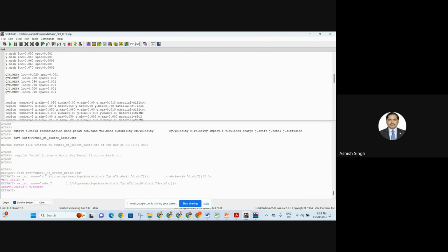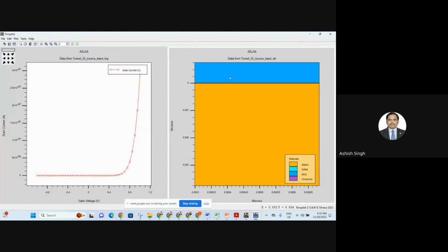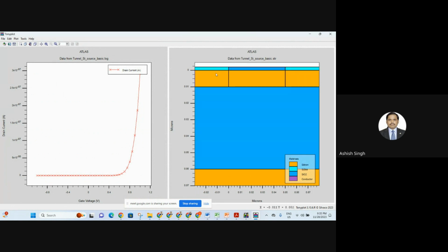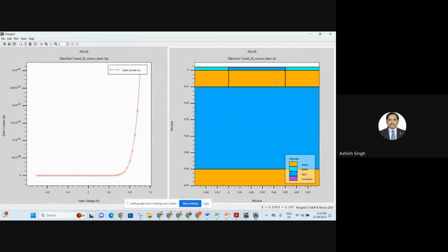Same. Quantum tunneling I have also discussed here. This is the junction, the junction for source and channel. Minus 20 to 20 is the tunneling region, and Y direction 0 to 10 nanometer. Same here. What is the value I have to consider? Minus 30 to 70 nanometer. So minus 30 will be right here and 70 here. For that also y is the same, so I have written y one time only, not writing the same value again and again.